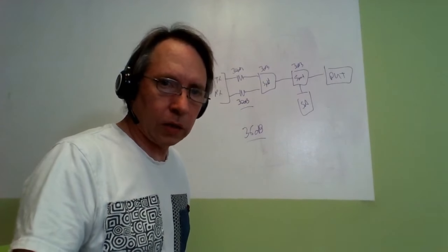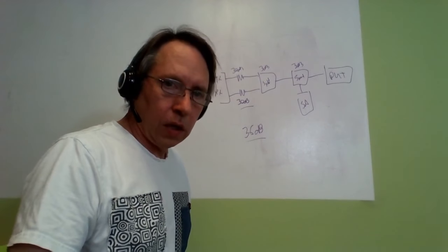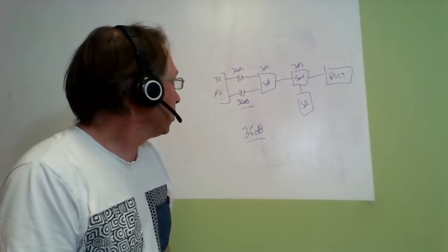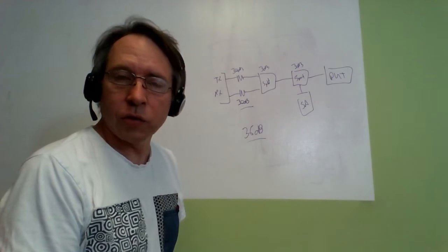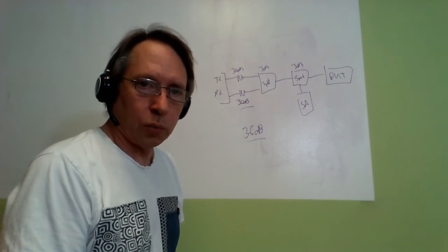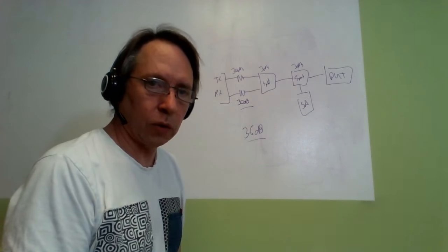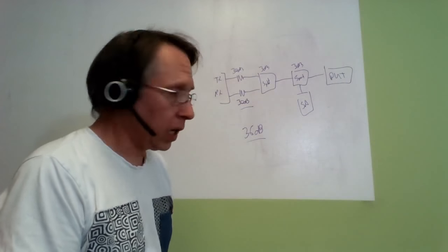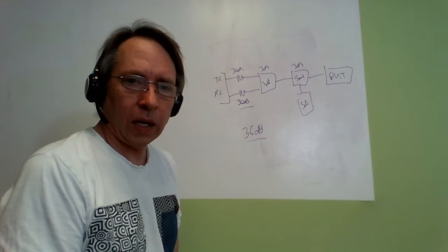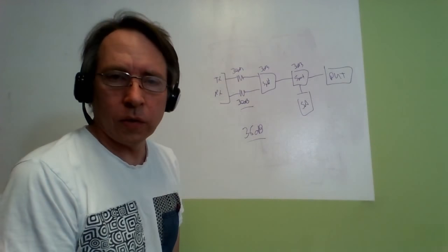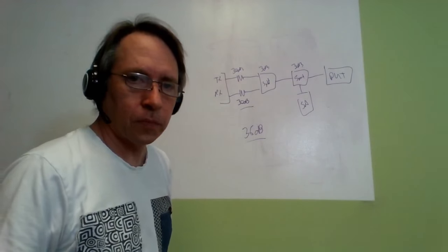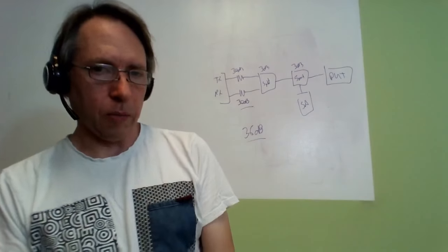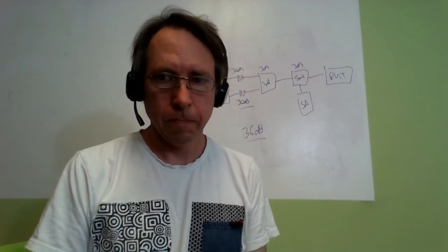And if we go back and look at the reported path loss in this connection right now, we see that it is 36. And what that tells us is that this connection is working just fine. This particular device under test is reporting exactly the path loss that we would expect it to report. If that number were significantly larger than 36 in this particular case, that would tell us that there's some problem in the device under test. Maybe a bad solder joint, a bad connection, a bad cable, something like that, or maybe an assembly problem.